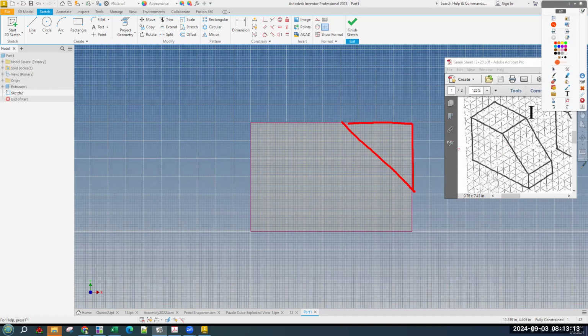and then cut extrude it. The key is we need to know where this line goes. For any sloped line, you don't need to know its length if you know where it starts and where it finishes. If you know where a line starts and finishes, you know the line. Okay, so where does it start and finish? Well, it starts here, which is up here, which is 5 blocks away from,